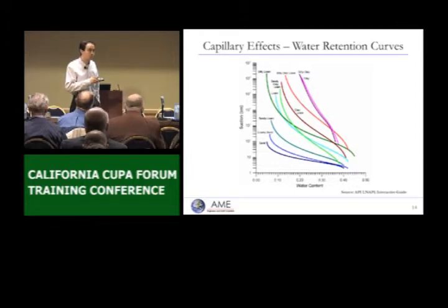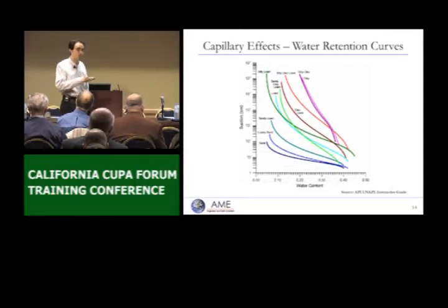In other words, the higher the negative pressure. So think if you go to the field and you try to dewater a sand column, let's say at 20% water content, you at least need to overcome this much pressure in order to put something in it, either air or oil. So that gives rise to the concepts of air entry pressure, and water entry pressure, all that.